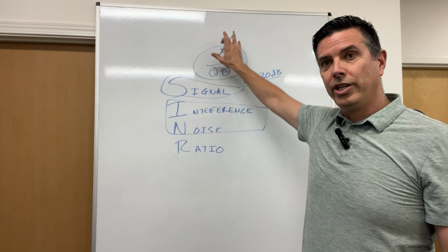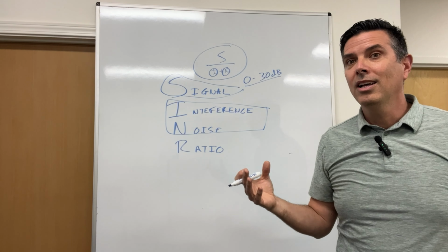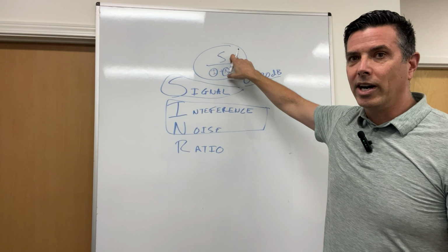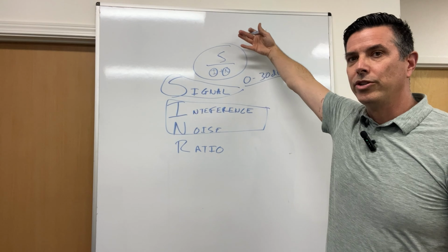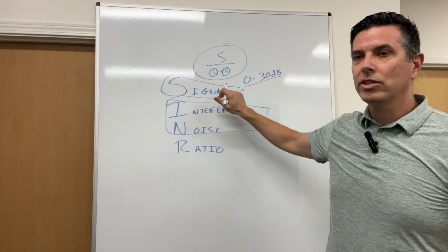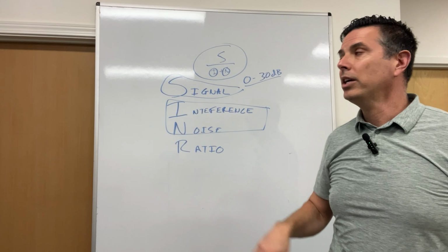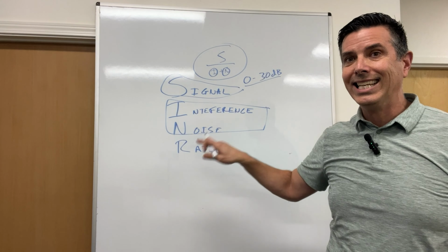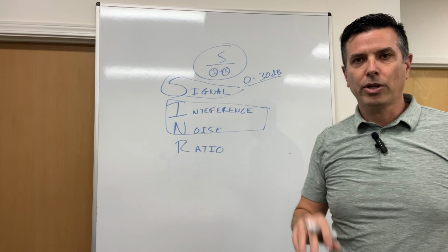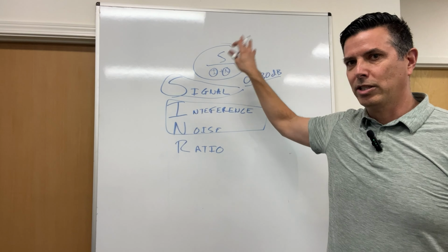But because this is a ratio, if you're in a situation where you have neg 95, neg 105, but your SINR is poor, you're close to zero SINR, you can turn your power up, you can increase the numerator of the ratio and do better. However, if there is interference and noise, it's better to weed that out. That will cause you more problems in the long run. So if you are dealing with a poor SINR condition, it's better to clean it up than try and beat it up with power. So that's a little bit of a brute engineering tactic. Better to clean it up than try to smash it with power.